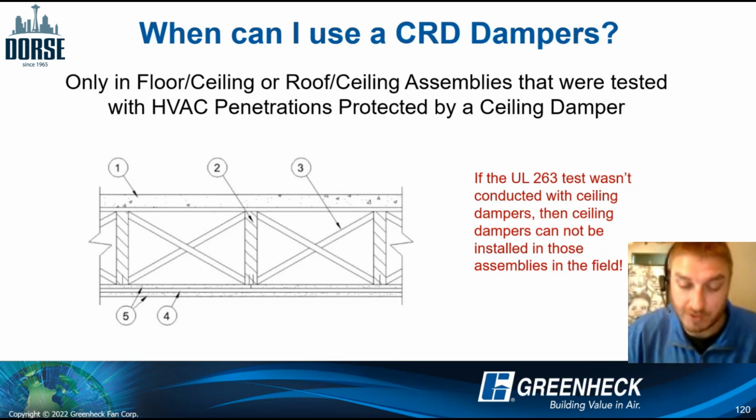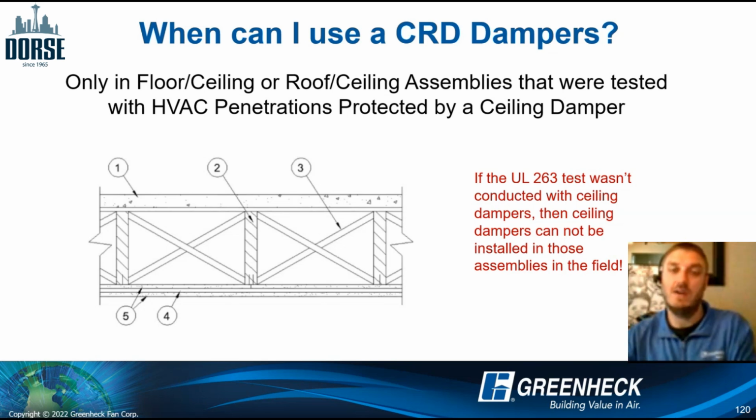So again, very important to know what your UL design number is. Look that design number up. It'll give you a drawing. It'll give you a listing of what's allowed in that design. You look up something like this, we just see gypsum, we just see truss. We don't see an opening, right? So no dampers allowed if you don't see it in the design.